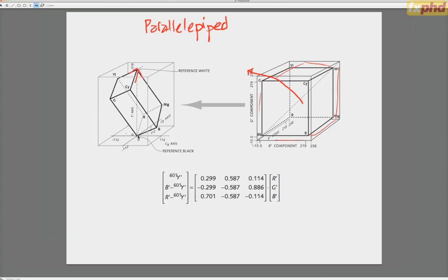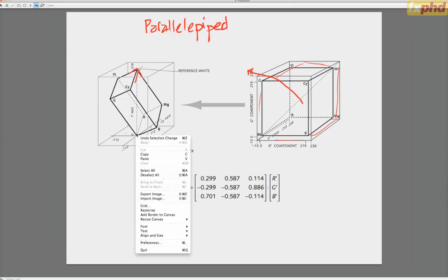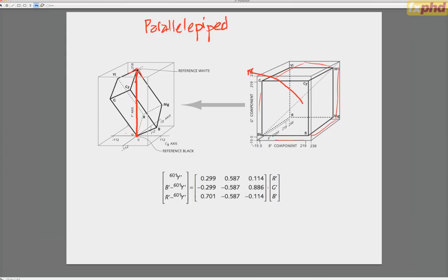So basically, we've gone to our representation where the grayscale in the original cube is now just the luma component, which is the vertical axis in this coordinate space. And the other two axes are the CR and the CB. And the advantage of doing so is we can filter in this domain as long as we maintain all the luma information. Now, there's a very interesting aspect of this mapping, which is there's whole fairly large regions here of space which are not occupied by so-called legal colors.